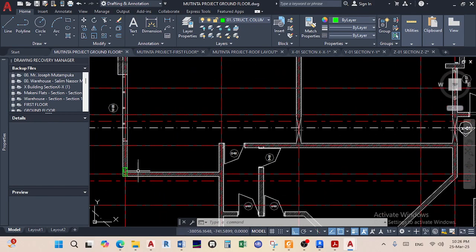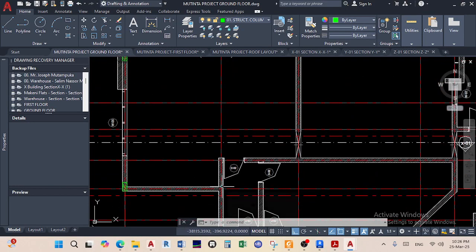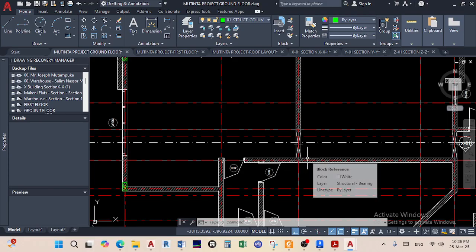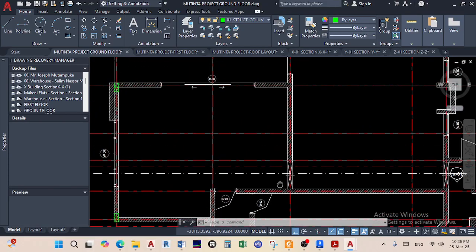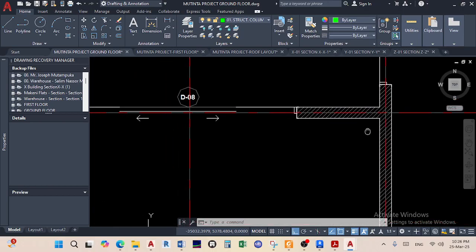I mean, if I put a column there, meaning a beam will run from there to there, and then from there it can only anchor here, meaning it has to be a secondary, and then this would have to be the primary, meaning the smaller one would be transmitting to the bigger one. You get?